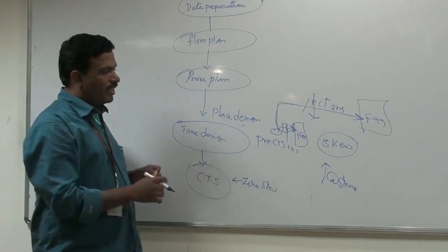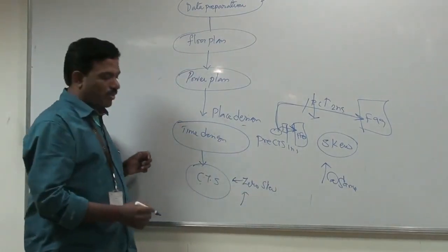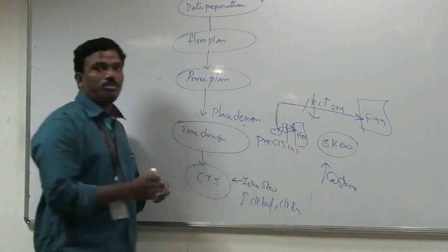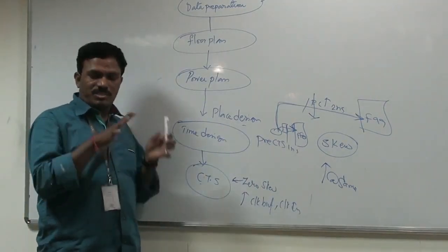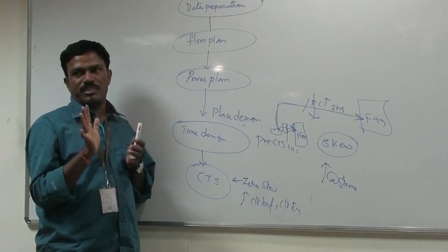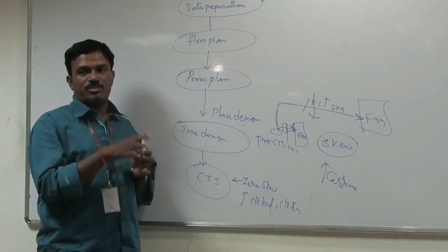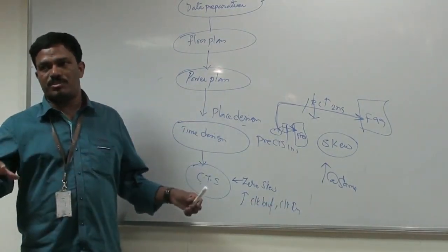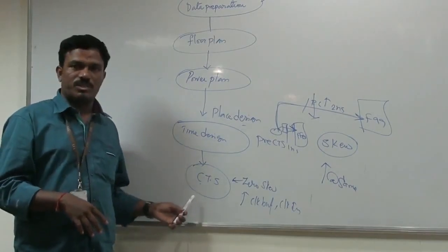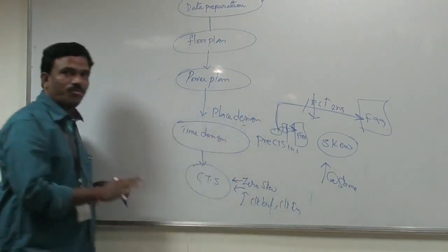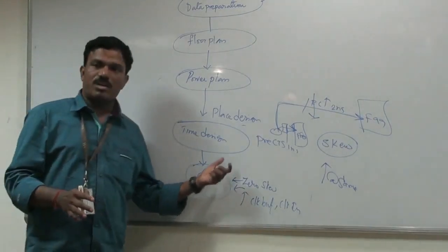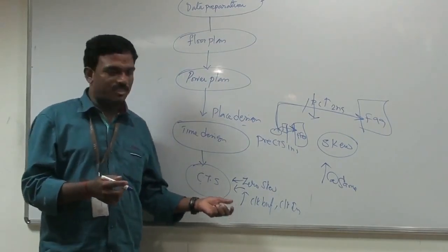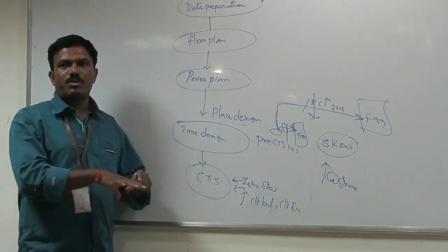In this process, we are inserting two important components, called clock buffers and clock inverters. These are the two important components we insert into the clock path. We are playing only with the clock path, not the data path. So only the clock path is optimized with this addition of clock buffers and clock inverters, and skew is optimized. Once CTS is over, there will be an addition of components, since we are adding buffers and inverters for 10K or 20K flops, based upon the design size. Once additional buffers and inverters are added, we will have some timing issues.